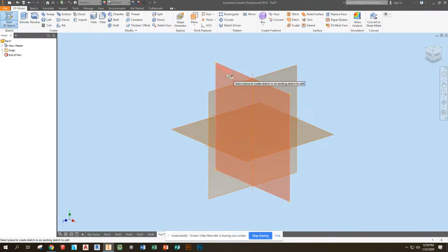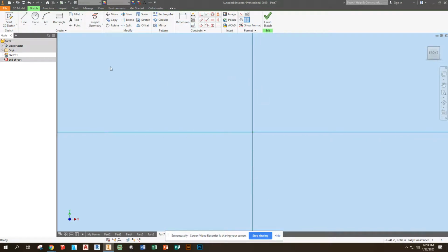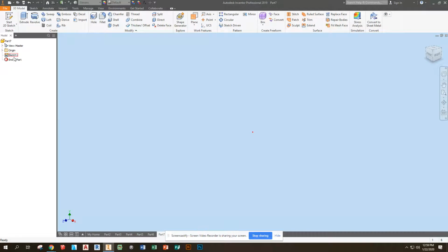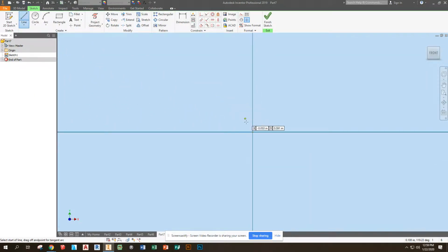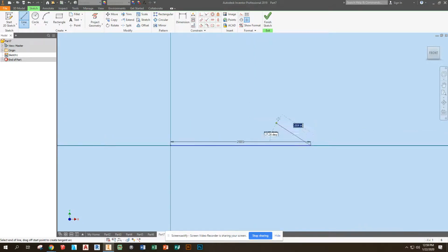start a sketch, the surface. This one I'm going to do a couple of zigzags on, so I'm going to start with a, whoops, I did start a sketch, I'm already in a sketch. Edit sketch, you twit. All right, so I'm going to go right here, start at that origin, go out this way. Now this one's going to be about, say, 2.75 this way. You'll see why shortly. I'm going to come up, straight upward, say about 1/2 inch, straight back this way to about